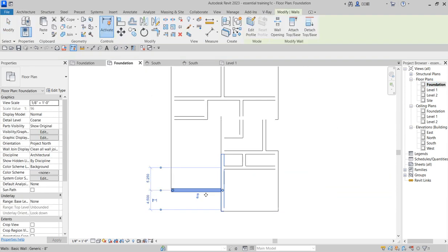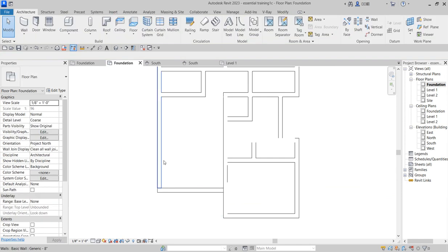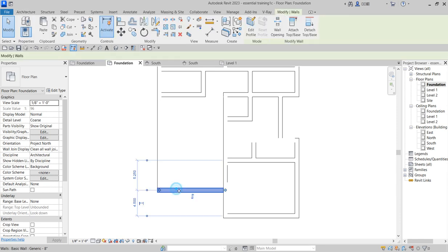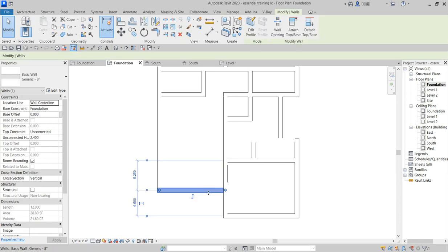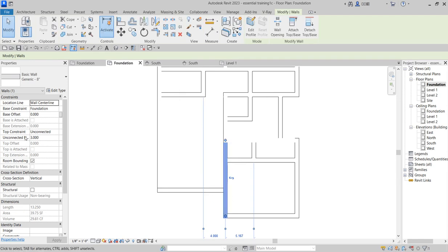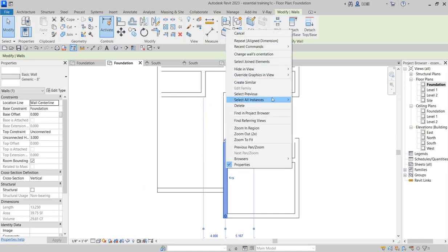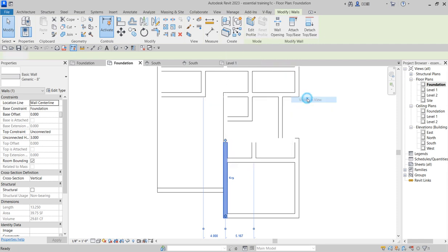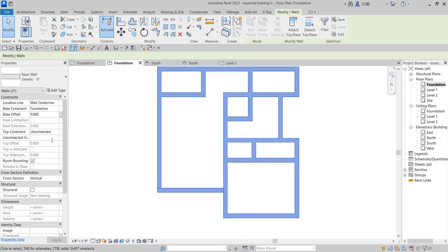So when you go to the foundation, is it visible? Yes, that's what it's saying now. So you know that this is the normal height of this. Okay, let's leave it like that. So you click on this, select, and say select on instance. In this view, you are going to see that this unconnected is not going to be showing that particular number again. Select all this view here, select, then you change the phase to 2.2 meter, apply, or let's say 2.